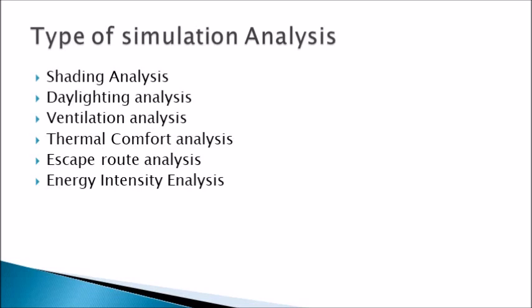Or even if you put shading on your opaque walls, it helps reduce energy absorbed in the walls, which later on will be transmitted into the building. Okay. You can do daylighting analysis. You can quantify what is the level of lighting in your building. Should you put your window of certain size? What happens if you put the shape of your windows this way, or how you distribute your openings? You can use this simulation package to do daylighting analysis.